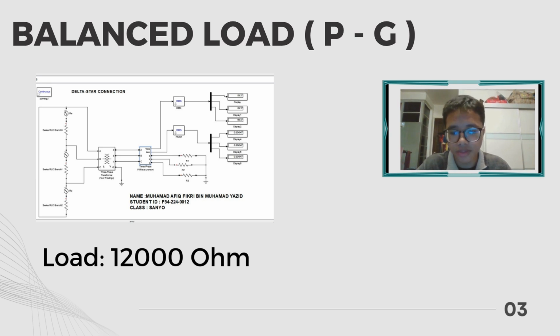Now for the power and balance, using the formula for power in a three-phase system, P equals square root 3 times V line times I line, we can estimate the total power delivered to the load. Plugging in the values, square root 3 times 178.1 times 0.0247, which is 7.73 watts. This tells us that the total power consumed is relatively low due to the high resistance value, which is typical in simulation studies where the focus is on current flow and phase behavior rather than power consumption.